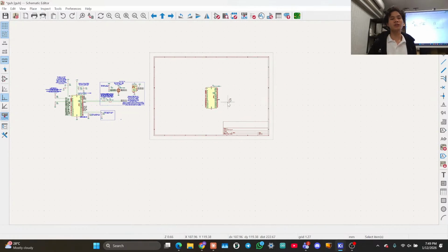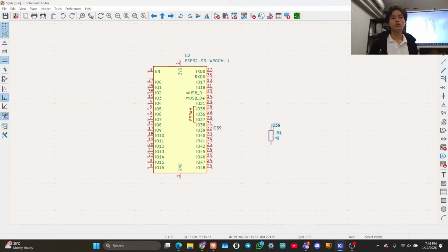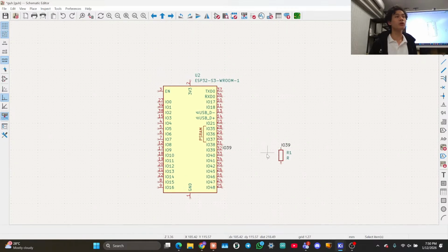So annotate your schematic properly and group related things together so that people will look at it and be like, ah, yes, this is related. Because it's very annoying if you have to read every single net label. What if you have 1,000 net labels? Then at some point you start to lose track of everything again. Okay, so any questions about net labels? Anyone okay?